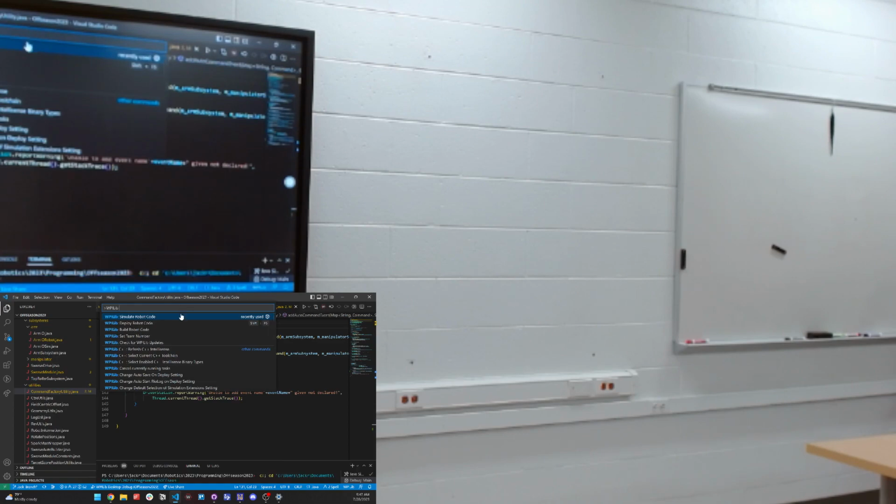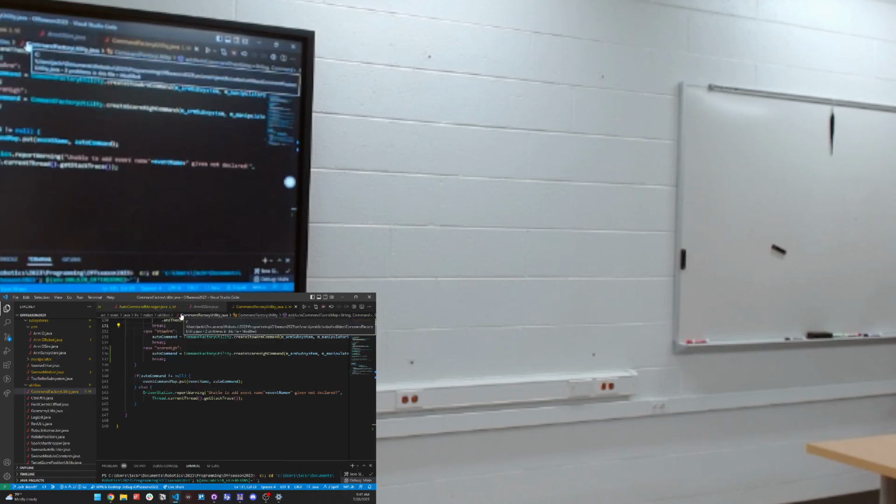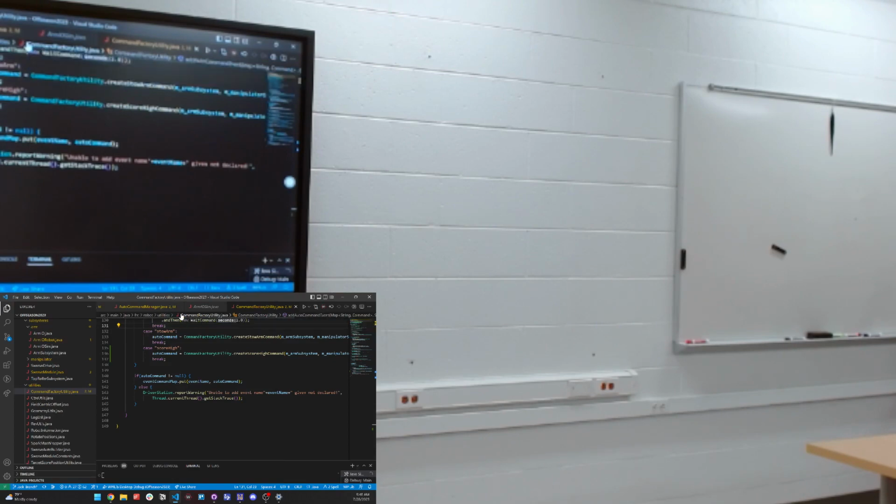Is it a similar process for the drivetrain, for doing the field poses? Yeah, the pose is actually much easier. You just have to take your odometry Pose2d and keep mapping it to a Field2d object, and it takes care of everything else for you.